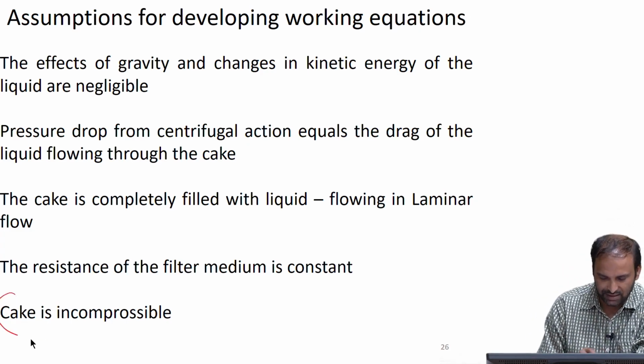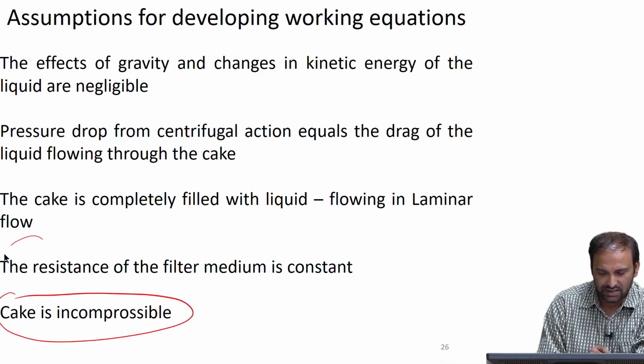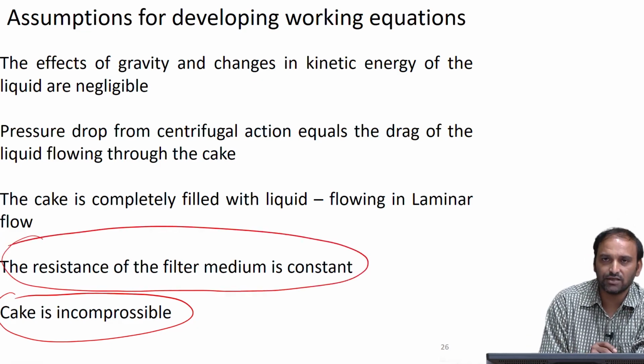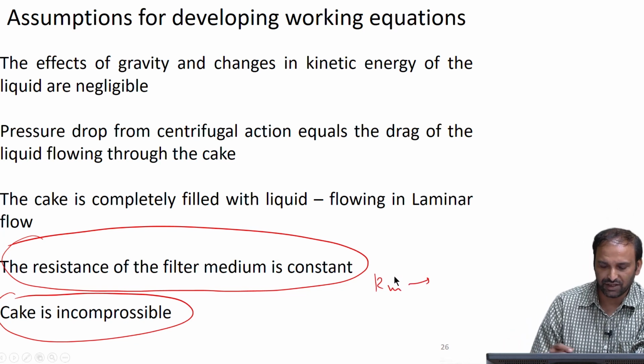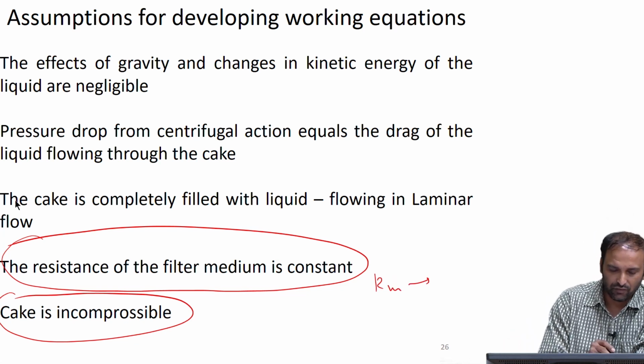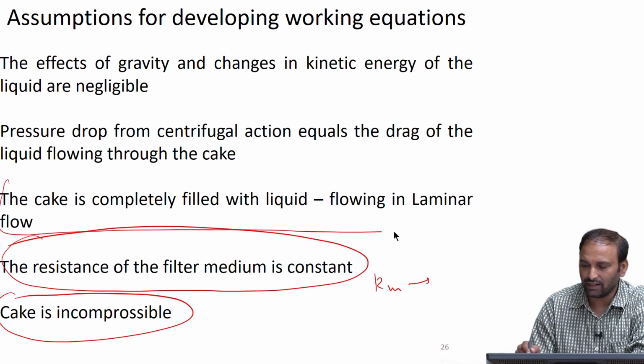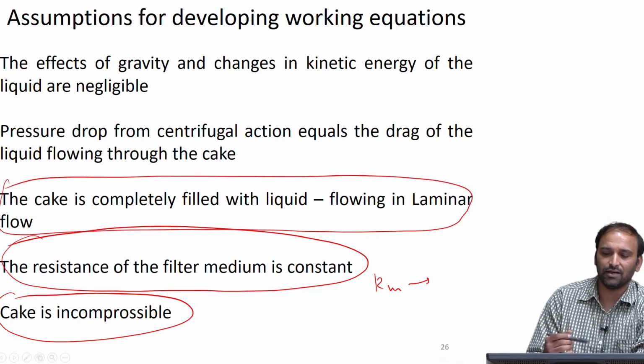Of course, there are some assumptions that are important when you develop these things. We are going to assume that the cake is incompressible, the resistance of the filter medium is constant, that means Rm is not changing during the course of filtration, and that the cake is completely filled with liquid such that the flow is laminar.